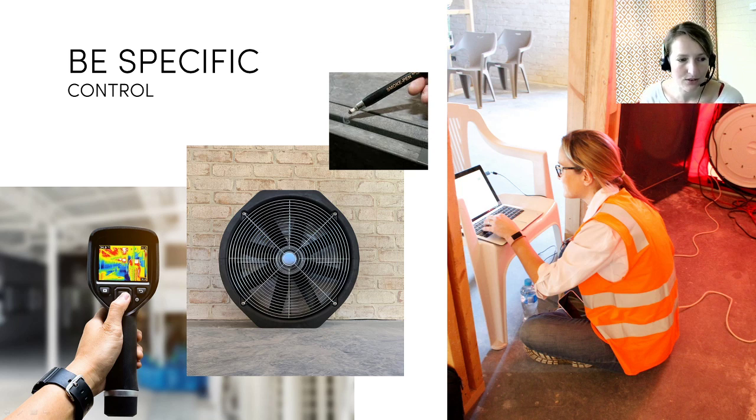Yes, so condensation is part of the new NCC, and there are also some aspects of thermal bridging coming into the NCC 2019. Now, all of these aspects are not compulsory, and the path is not completely finished with that. But I think it's our responsibility when we go for this kind of building to gain the maximum knowledge and give the client the possibility to go the whole way with those aspects.